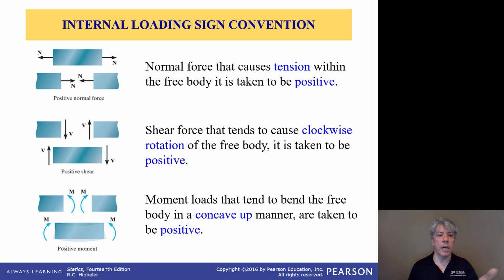Or if you look at the cut body third down on the left, you'll notice that we've got a downward facing shear on that cut face. Now, the rest of the body's not shown. There's a wavy line indicating there's more to the body going out on that side. But that shear force is a positive shear force on the cut face, and in any shear diagram, because it tends to cause clockwise rotation of the body.